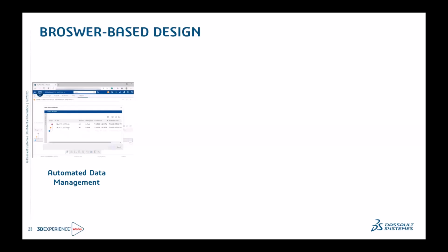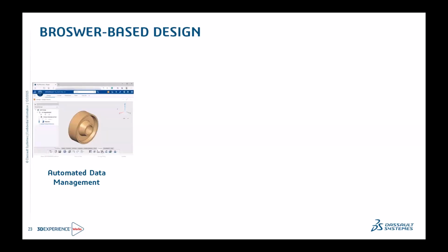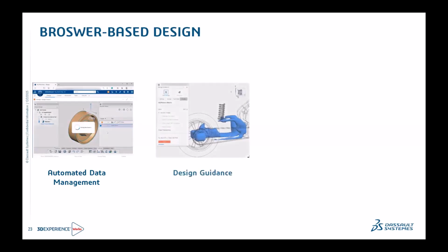But the platform has data management that is already embedded in the system and it's automated. So you have the ability to create revisions. You can, for example, check in and check out files. You can collaborate on the same design and do real data management without needing to have a server because it's included and it's, let's say, part of the process in a natural way.